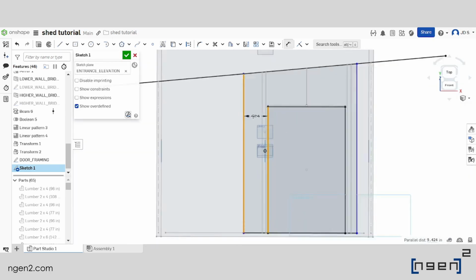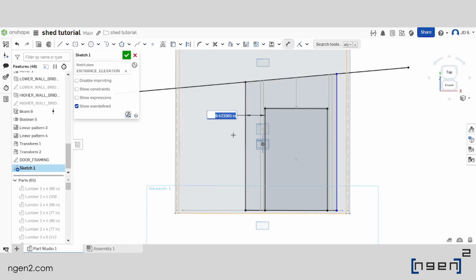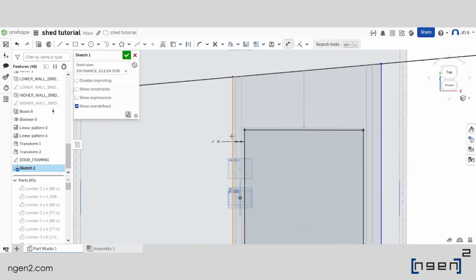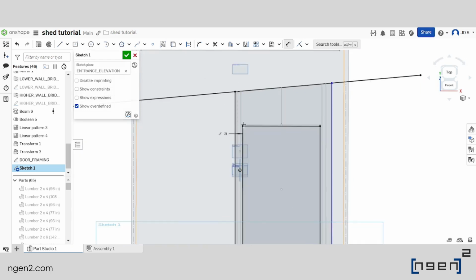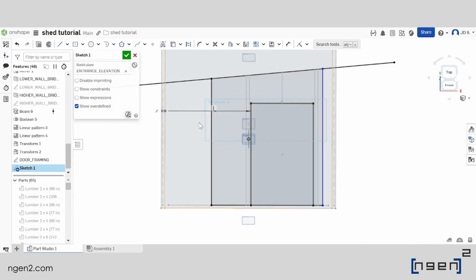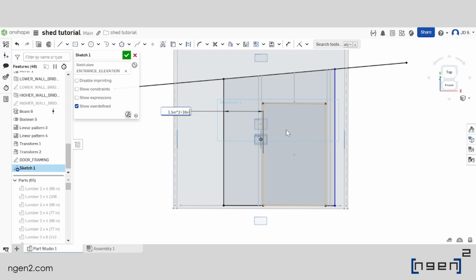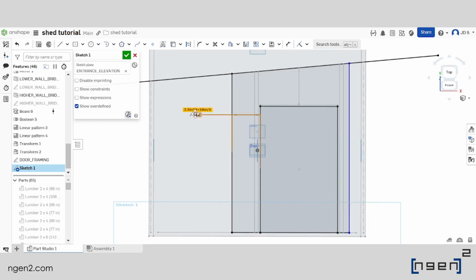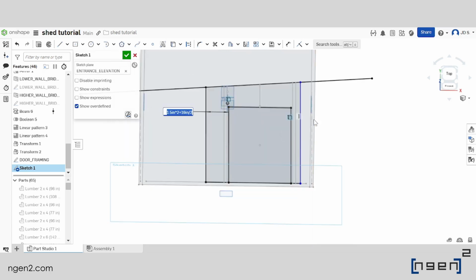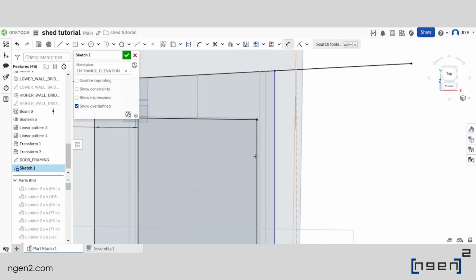On the left side, we will dimension the offset as 1.5 inches times 2 as a starting point. This will cover any framing that's in the way of the king studs. We will add an additional 16 inches divided by 2, which is 8 inches, to remove any other framing in the way. We will copy this formula and bring it to the right side.